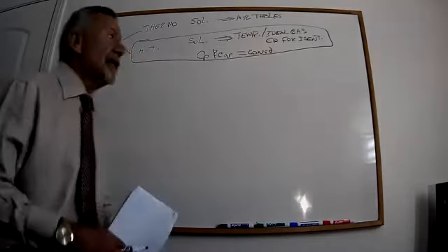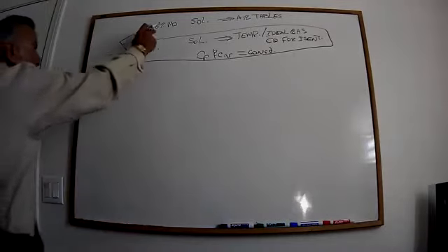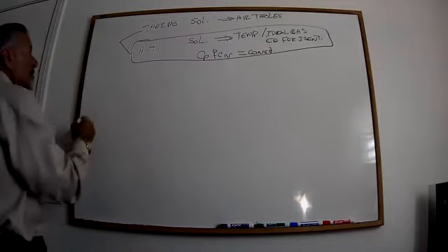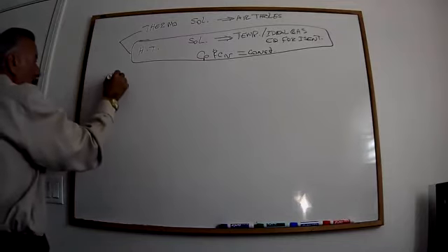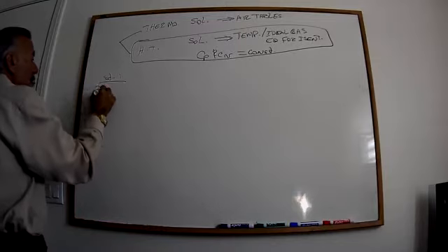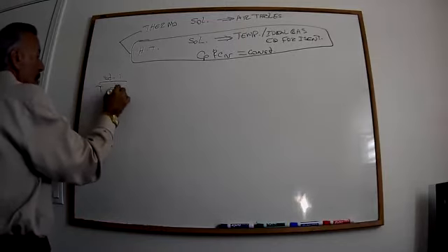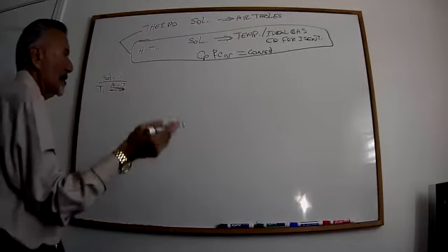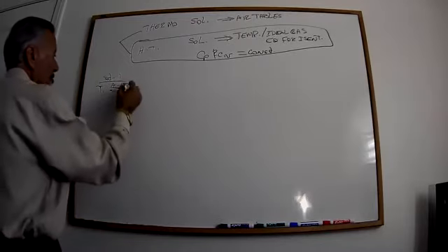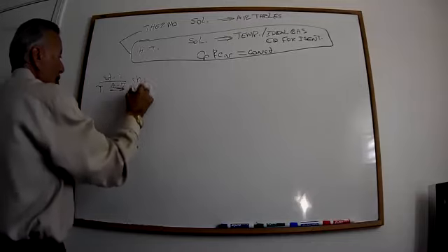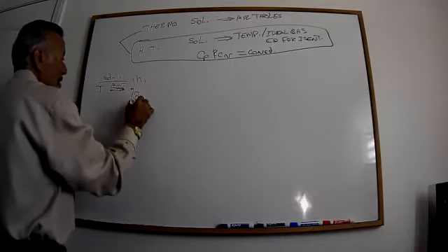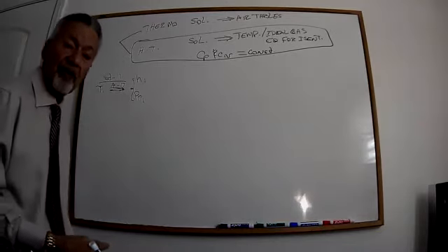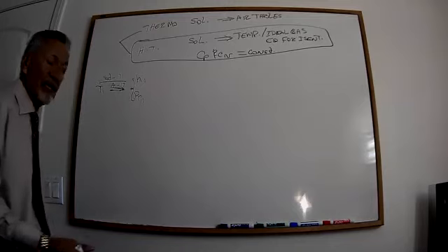Okay? Now, here, for the thermal part at state 1, based on T1, you go to the table, A17 or A17E, depending on the system you're in. You find H1 and PR1, before you find the VR1, because you have a compression ratio.